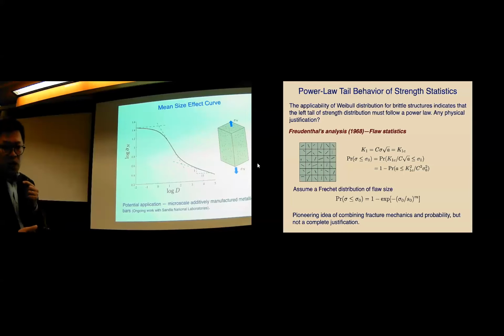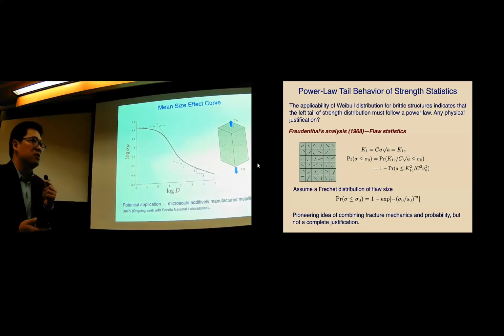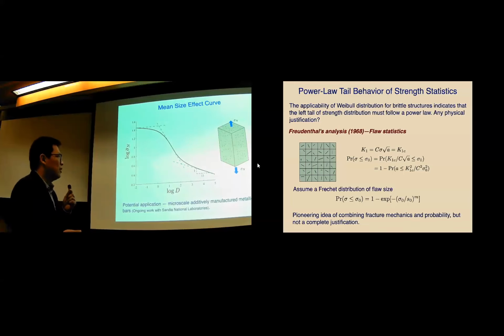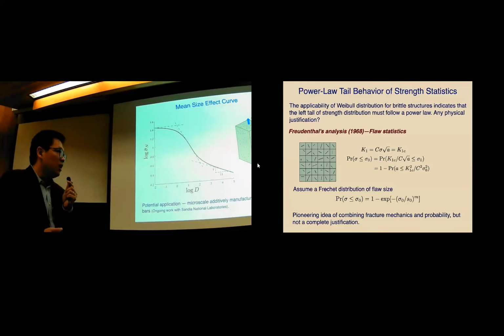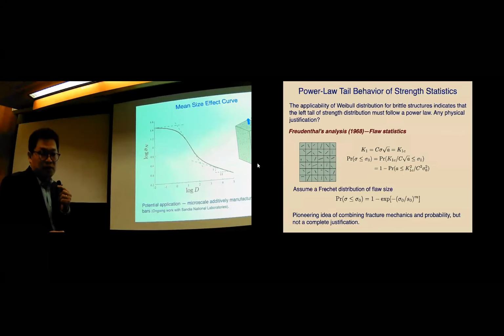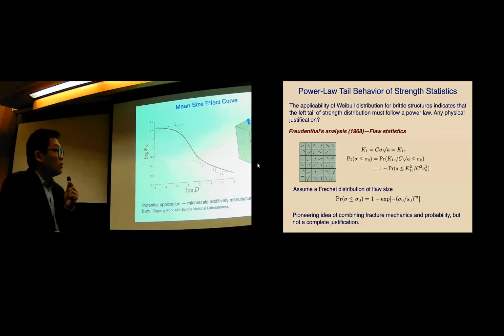On the other hand, another application of this model we are looking at is that, as you probably noticed, I have to work on a stationary, homogeneous process. I cannot go to non-stationary, it will be super difficult. So another thing we work on is to use it for stochastic finite element. A fundamental problem in stochastic finite element is how we can map a continuous random field of material property onto the finite element mesh. That projection method currently is just averaging or local projection. But for localization instability, we believe that sometimes we need to take a minimum. So how does the minimum in a 2-dimensional random field project to a single point? This level excursion can do the work for us. So that's another application to combine in stochastic finite element simulations.